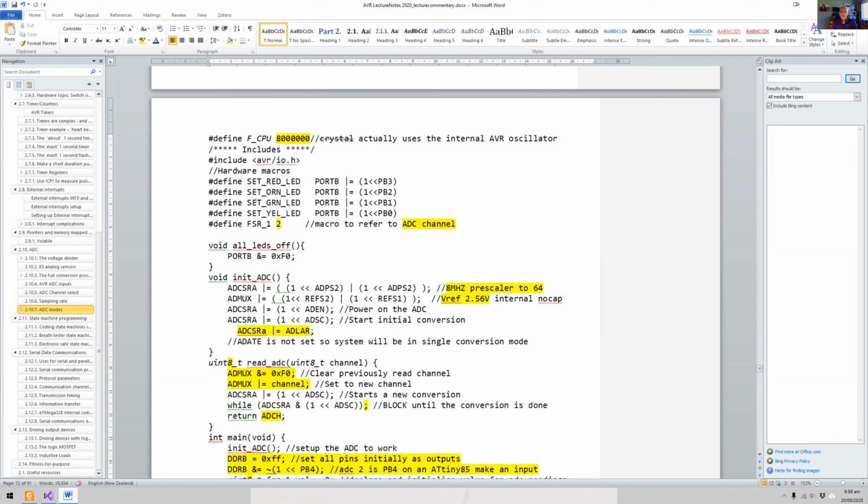This little ATtiny85 only has port B. It doesn't have port A, C, D, F or G. It's just got port B, and of course it's only got about 5 pins, so that makes it useful for a few little things,